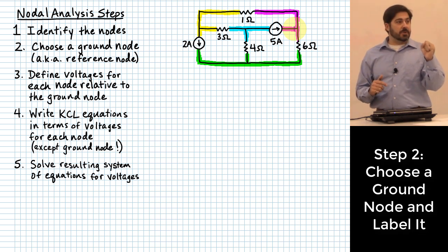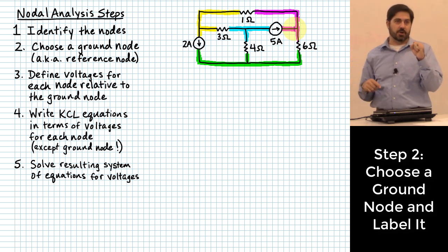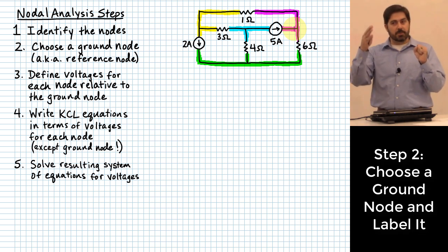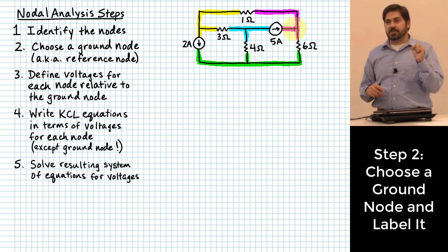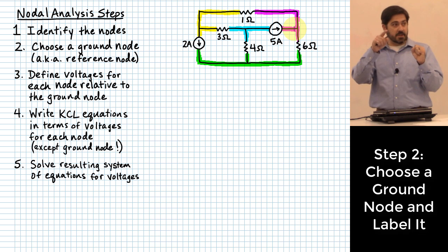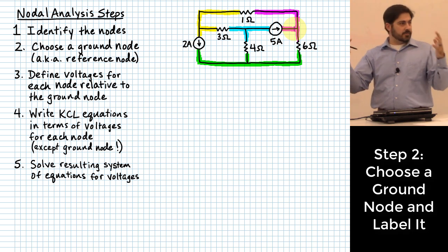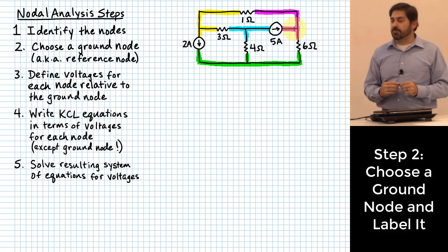Technically, it doesn't have to be. All we're saying is that we're going to pretend like it's 0 relative to all the other voltages that are in the circuit. Okay? So that when we say there's a voltage at a particular location, we don't necessarily always have to say relative to this node. We can always just sort of assume we mean that's a voltage relative to the reference node voltage, right? And we're essentially going to assume that that reference voltage is 0.